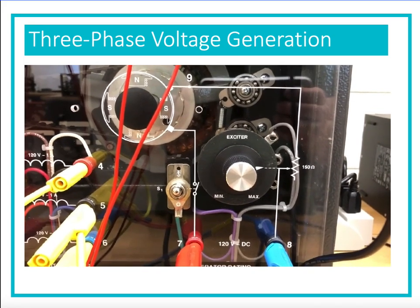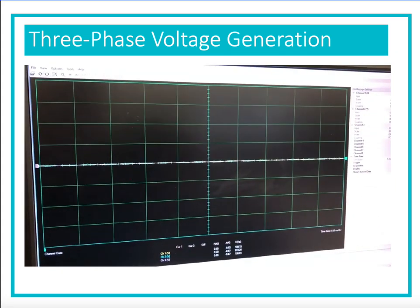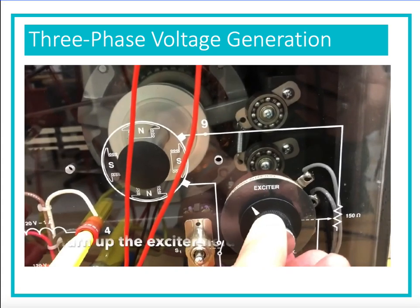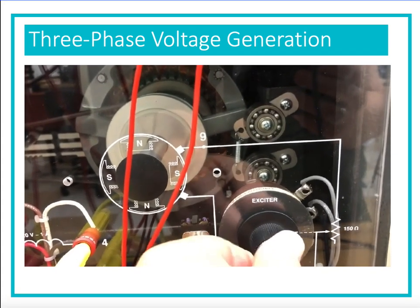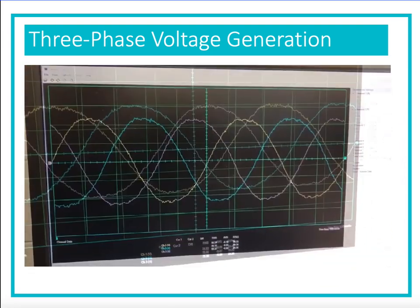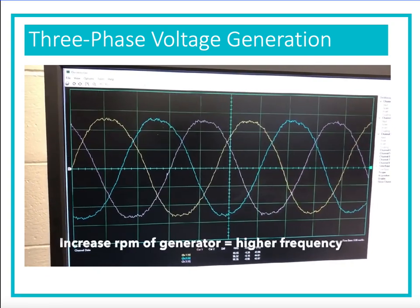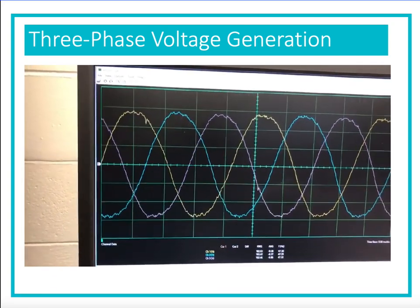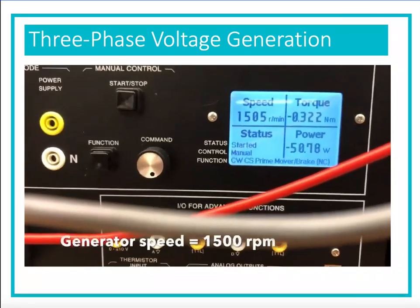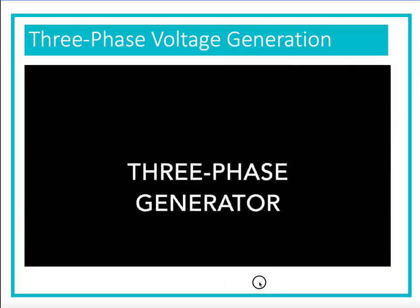And we can start it running. You can actually hear the generator running now. We turn up the excitation field, and we get more voltage, not a lot more, just a little bit more. But if we turn up the RPMs, we get a lot more voltage and a higher frequency. So that's basically a very short, brief explanation of how the voltage is generated.